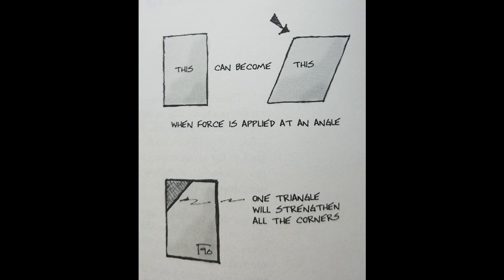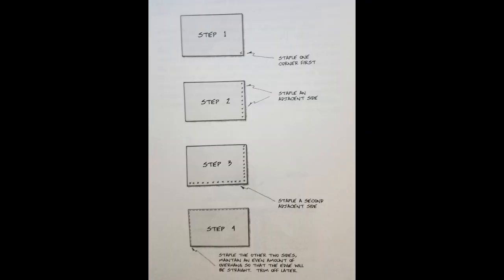The face or the skin of the project is usually Luan in most cases when it comes to walls. This is again because it's a fairly lightweight material and it's easy to work with and attach to the project, as it is a little more brittle and a little more malleable than plywood. It also has that fairly nice finish, as we talked about earlier. So whenever you get to painting or anything else to do the finish work, you get a pretty good look, versus if you try to attach plywood to the face of these walls, you would sometimes get the defects that you would see in plywood.